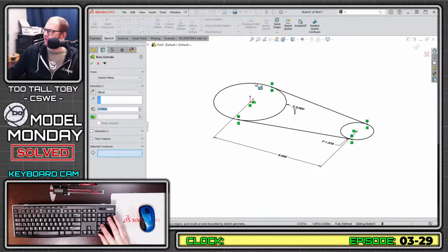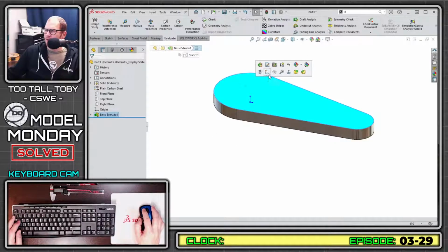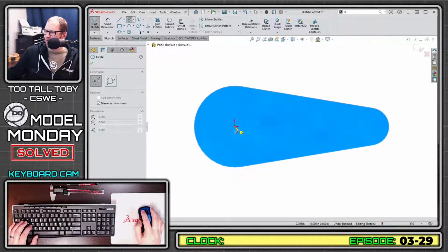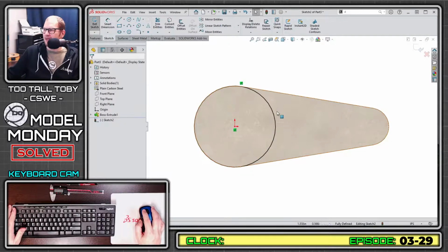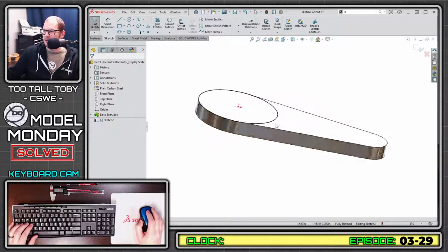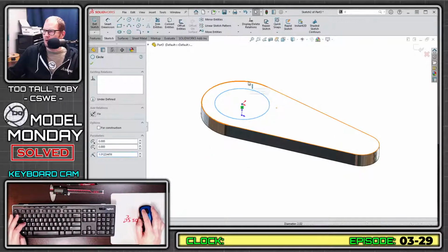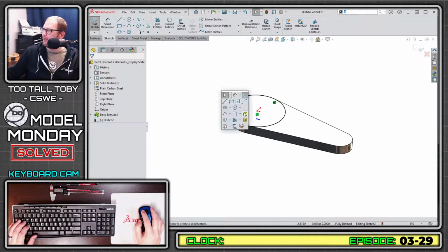S key extrude. This is going to go up to a height of 0.5. Enter. Pick the contours. Right mouse button to finish that command. Select face. Begin to sketch. Orient your view. And S key circle. And now this circle is going to start here, and it's going to come over to this point. If you pick the point of tangency, then you can get that to be fully constrained all in one shot. If you don't, then you could always pick one, hold control, pick the other, let go of control, make co-radial. That definitely works. S key, extrude.